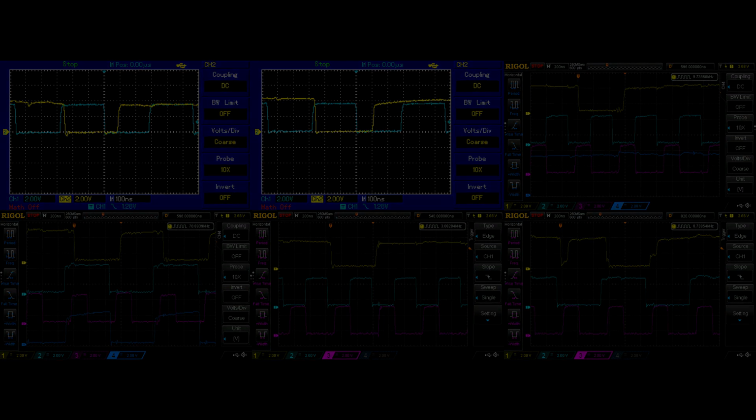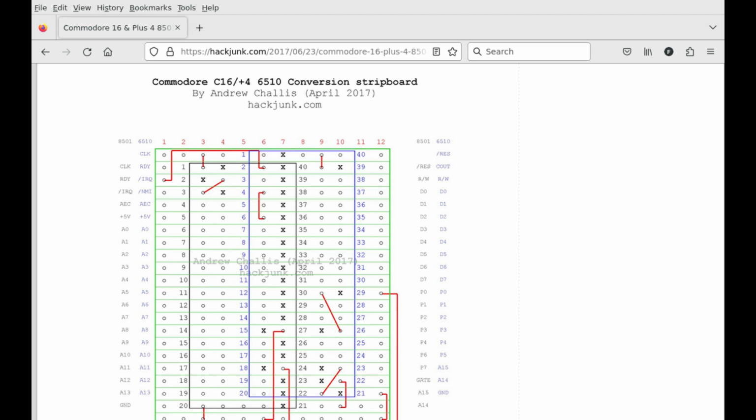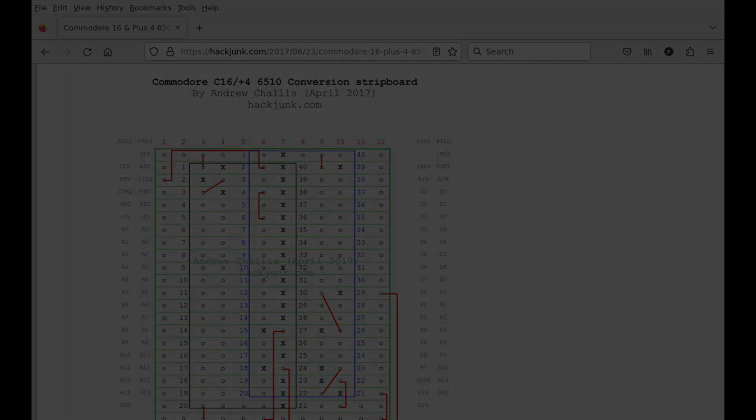Thanks so much, Gerrit. Of course, I think everyone knows that the 7501 CPU can be substituted with a MOS 6510 CPU with a socket adapter and some kernel patches. In this web page you can see such an adapter. But the 6510 has no gate signal input, so why this new CPU was really needed remains to this day a real mystery to me.